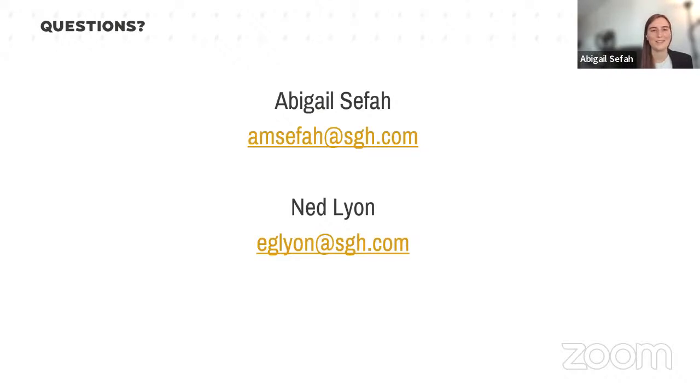Yeah, this is a really good question. There are a lot of answers. Typically, if we're doing a historic renovation like I've been talking about today, we want to be consulted early on to try to figure out, before it's too late, if this is actually a good design strategy. But I've also been on projects, especially new design projects, where throughout the construction process there will be changes and the contractor will come to us and say, can we make this change at this soffit condition? And so we'll run a WUFI model or something to try to figure out if that change would be acceptable or if it would be harmful. So I think really at all stages of the design process, it can be used.